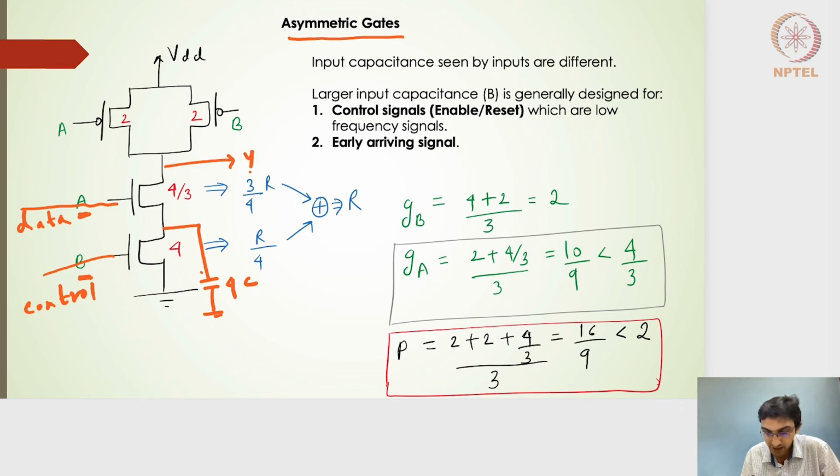Because it occurs very rarely, when the output here has to fall from 1 to 0, right? Even this particular capacitance will discharge. All right. So this capacitance being more, 4C is actually derived from the width of 4 here. And because I have increased this width, this capacitance also increases, and then this particular capacitance has to discharge. Right. So this very rarely occurring signal, whenever it happens, this 4C capacitance has to discharge.